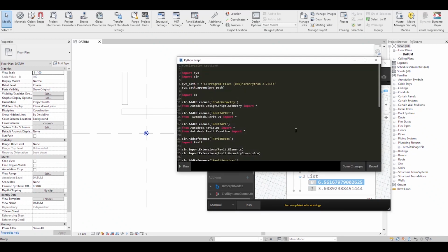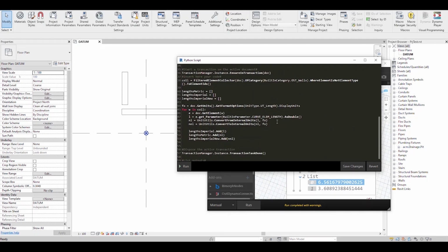It seems that this is quite tricky. But it's not. Once you understand that you have to handle these numbers properly, otherwise you don't get the proper, for example, measurements. It is important to mention that those conversions are also needed if you want to place a specific object in a specific location, because the X, Y, and Z are also measured as a length from the project base point, and so those are managed as well as elements using the internal units.